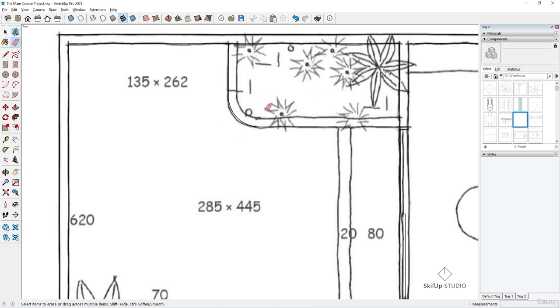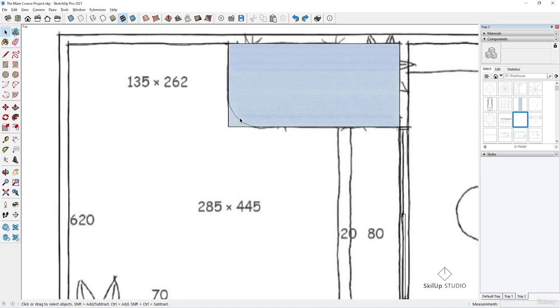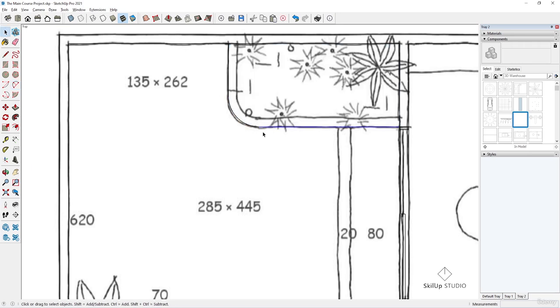Also, there is another way. If we have this shape, a face like this, and we know the arc start point, then draw the radius 50, then draw the arc itself. Hover over this edge, and once it's magenta, double click, and it will automatically delete the extended lines and give this shape. Delete this face, then select the lines we drew,